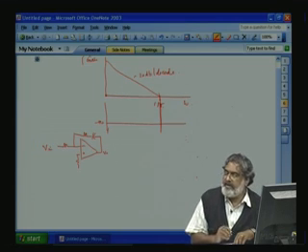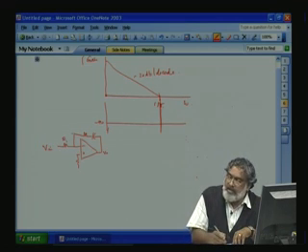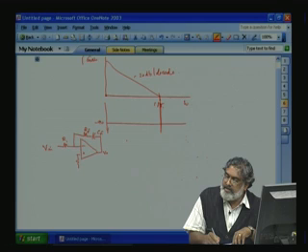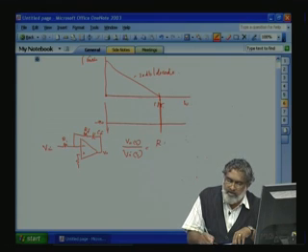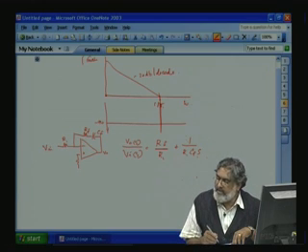This is our Vin. Here let this be R1, RF and CF. Here V0(s) divided by Vi(s) is equal to RF by R1 plus 1 by R1 CF S. So, the overall transfer function will be